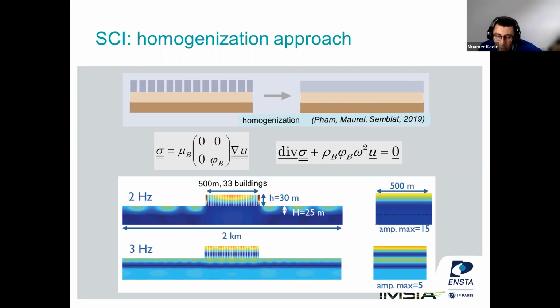So in principle, with these enriched cases, you would be able to go much higher in frequency and even to catch some resonance inside of your structures. Yeah, exactly. We mainly developed this enriched finite element model for seismic studies, but it may be used for dynamic excitation even in the higher frequency range.